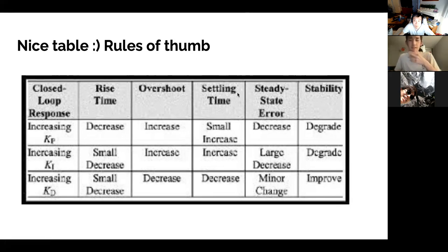This is the idea. If you see your drone is oscillating a lot, you have to tinker, for example, with the overshoot amount by decreasing these, maybe increasing this. And it'll be a trade-off in all senses. At the end of the day, you just have to get a range of values that actually works for you. So this will be very useful for you guys, hopefully.